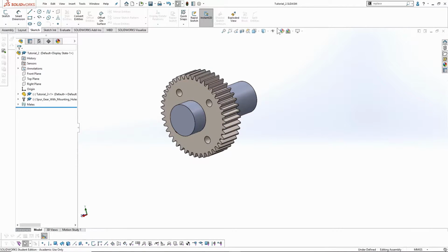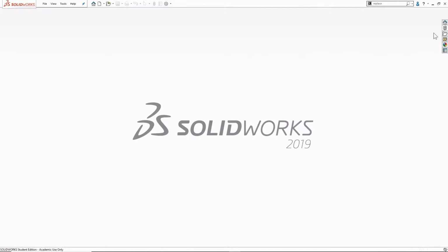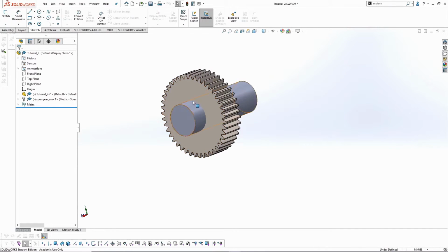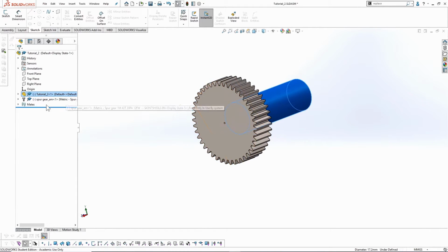But after closing and reopening the assembly, all the changes made to this toolbox component disappear, and in case of more complex assemblies, it results in multiple errors and warnings, which may agonize a beginner SOLIDWORKS user. The way around this is to use a tool that can be found in the installation folder of SOLIDWORKS.